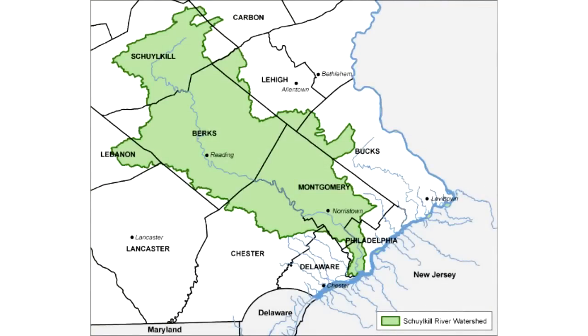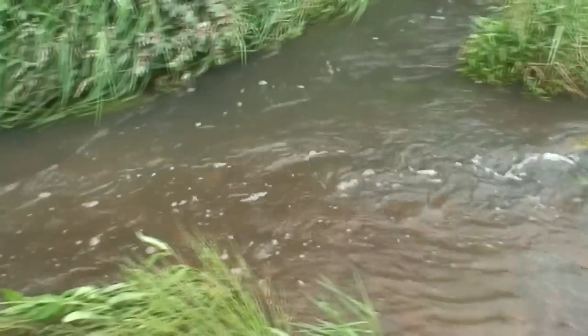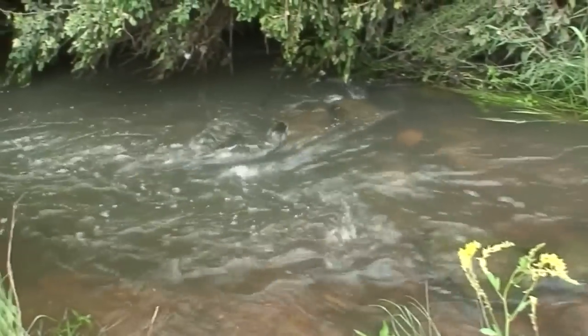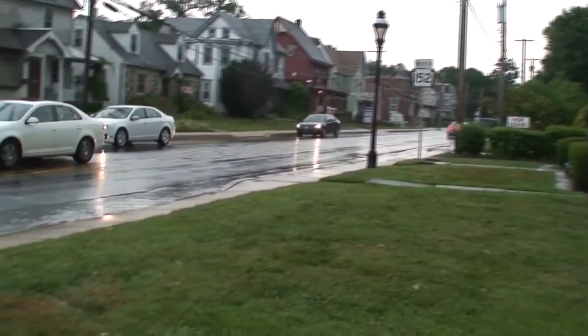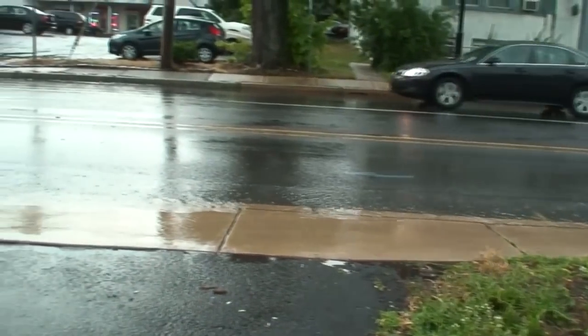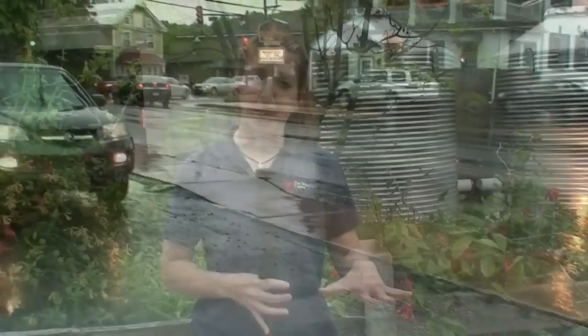When you're talking about a watershed scale, the best place to handle stormwater is at the headwaters and all along the watershed as you go downstream. The more you can do on a small scale, instead of letting stormwater become this huge issue with huge volumes where it's causing millions of dollars worth of damage on a municipal level, it's best dealt with on, you could even think about, a homeowner level. When homeowners are educated about ways they can help their communities and the health of their local environment by doing small measures, small practices on a home scale, most people are willing to do that.